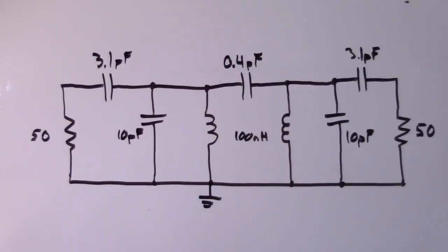So what I typically do is I make these capacitors variable. Just some trimmer capacitors so you can really dial in the center frequency of the filter. Now optionally, if you've hand wound these coils, you can pull the coils apart so they're spread apart a little bit more, or push the turns together so they're a little closer, and you can vary the resonance of these tuned circuits that way. But I actually find that to be very temperamental and really a pain to do. So I much prefer to have some good quality trim caps in here to tweak the center of the bandpass filter if necessary.